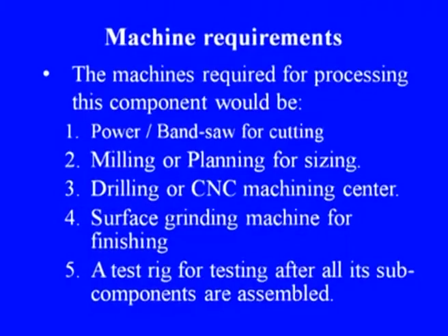Machine requirements. The machines required for processing this component would be power hacksaw or bandsaw for cutting, milling or planing for sizing, drilling or CNC machining center, surface grinding machine for finishing, and a test rig for testing after all its subcomponents are assembled.